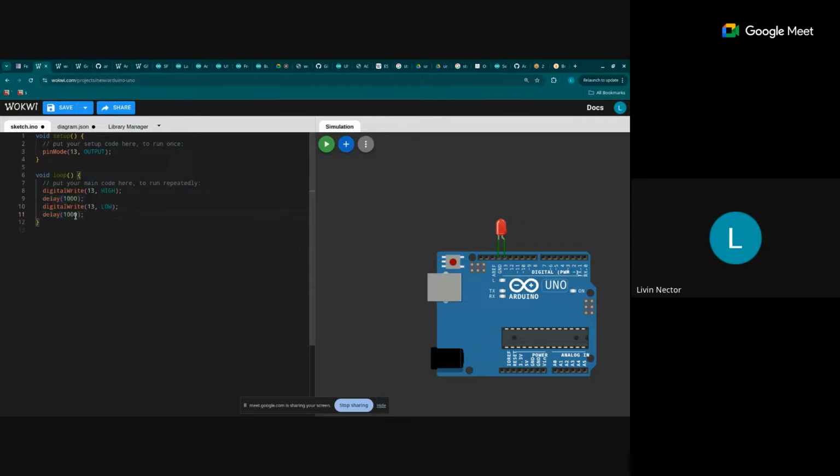So what will happen is, when this program is compiled and pushed, when it starts up, it starts with this. It sets up the pin mode configuration, right? The GPIO, general purpose input output, is basically turning things on and off. You can send control signals by turning this on or off. So basically, in GPIO, we are sending control signals.